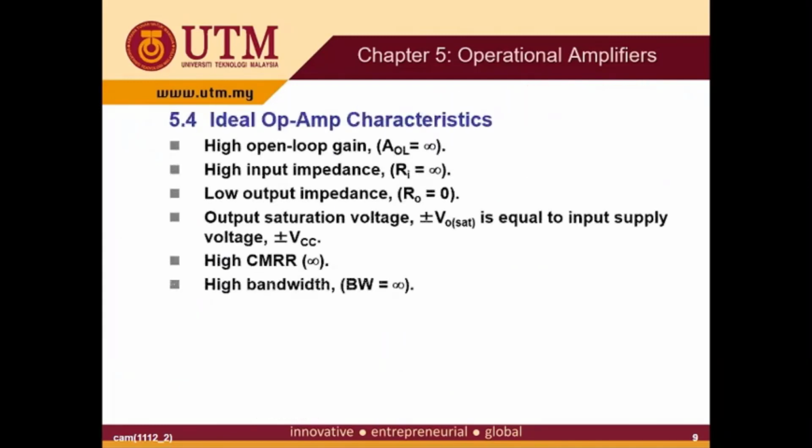Okay, some of these characteristics have been mentioned, so we just emphasize them again. An ideal op-amp will have infinite open loop gain, infinite input impedance, and zero output impedance.